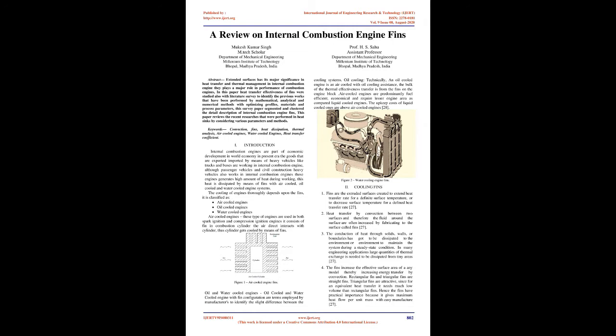Oil and water-cooled engines. Oil-cooled and water-cooled engine with fin configuration are terms employed by manufacturers to identify the slight difference between the cooling systems. Oil cooling. Technically, an oil-cooled engine is an air-cooled engine with oil cooling assistance. The bulk of the thermal transfer is from the fins on the engine block. Air-cooled engines are predominantly fuel-efficient, economical, and require less engine area as compared to liquid-cooled engines. The upkeep costs of liquid-cooled ones are above air-cooled engines.